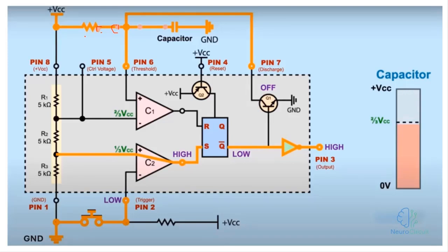and when my IC is in a state where pin 7, its transistor is off, it means there's no longer this connection here with the transistor. So, for example, pin 7 is not connected to ground anymore. Here, pin 7 is connected to pin 6, and the intersection of these connections is attached to the resistor and capacitor.